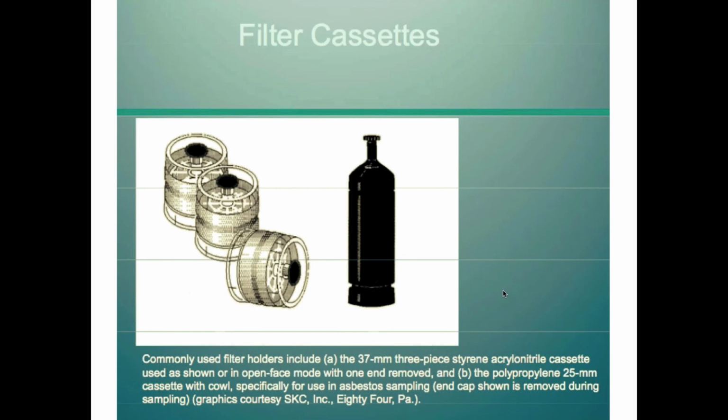What might account for an increase in weight on a fiber like cotton or cellulose that might not be the dust that you pick up in the air? Moisture, right? So PVC filter, you don't have to worry as much about it absorbing moisture. So that's one of the reasons why I use PVC filters for this particular application.